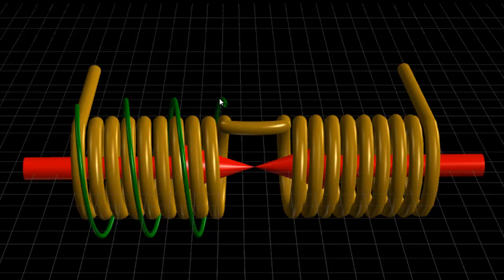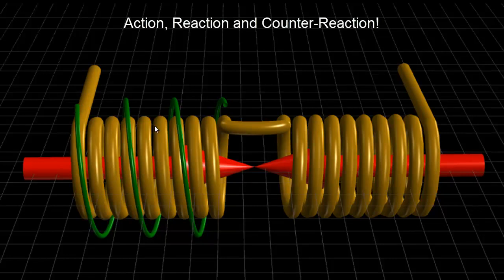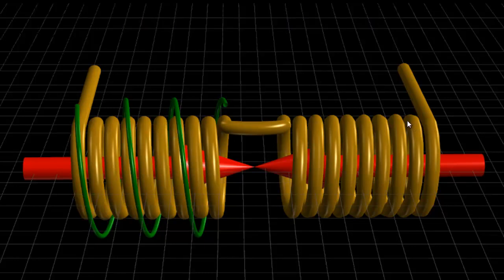So our green coil here must be the signal coil, if you like, for each coil, this coil here and this coil here. Our green coil introduces a signal into this coil, and that signal will be at a frequency and duty cycle that these coils will start to get excited and become, if you want to use the term, electromagnetically resonant.